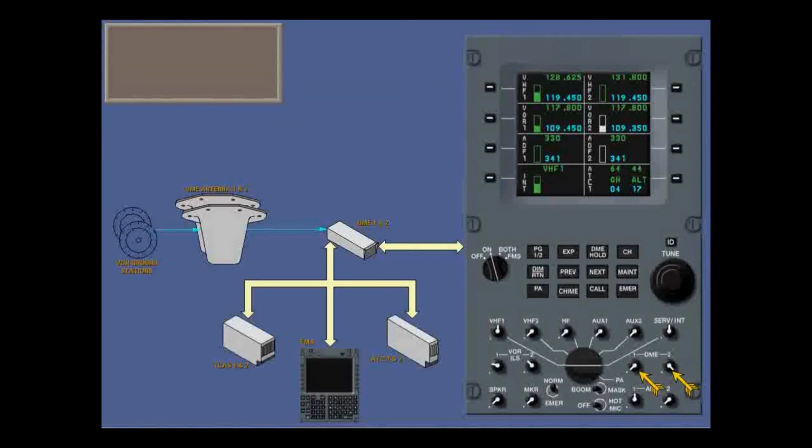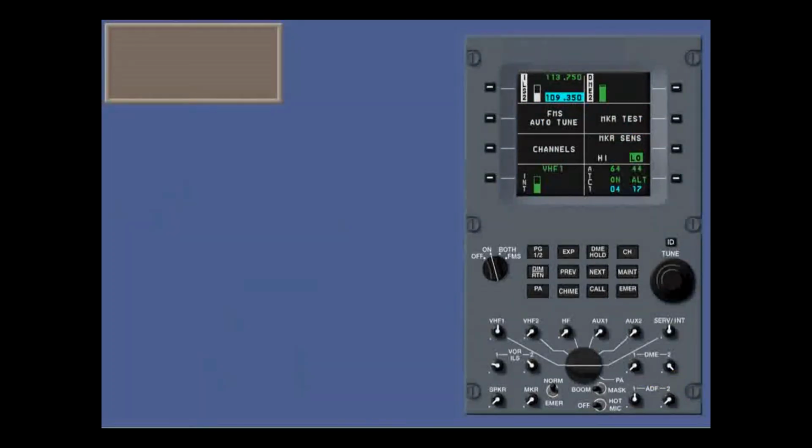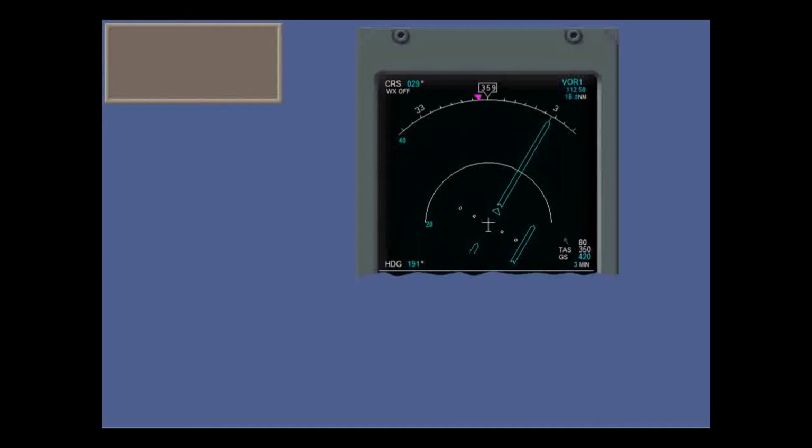As usual, you can listen in to the station signals and control volume on the ARC2. DME volume level is displayed on the VOR particular page. Outputs on the PFD and MFD are distance to station and time to station. Ground speed is displayed on the MFD only.